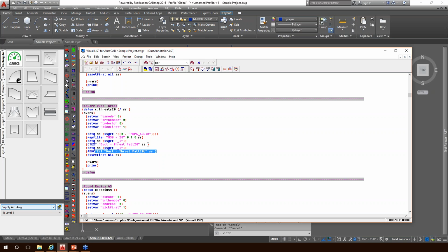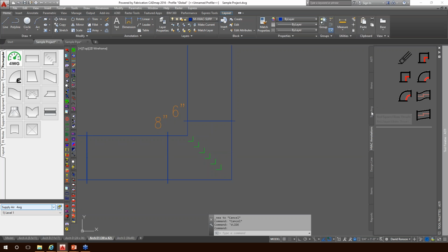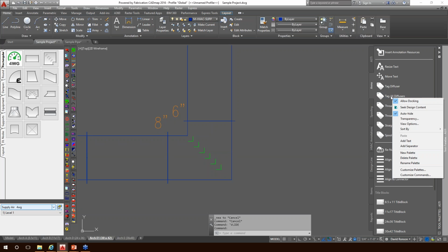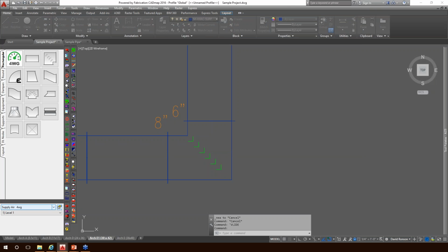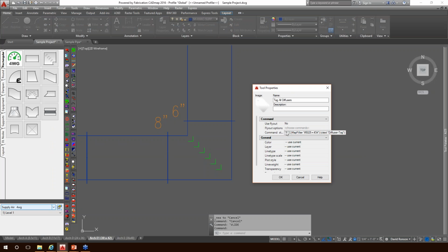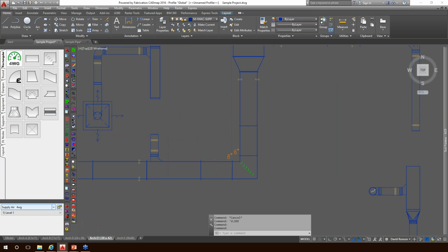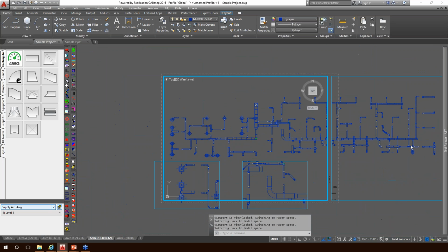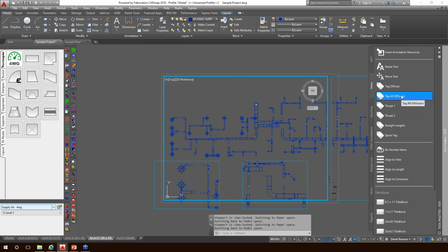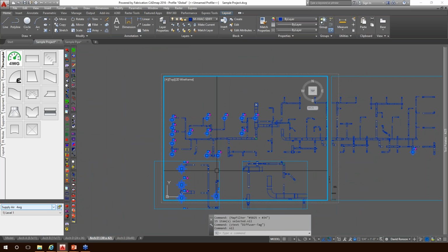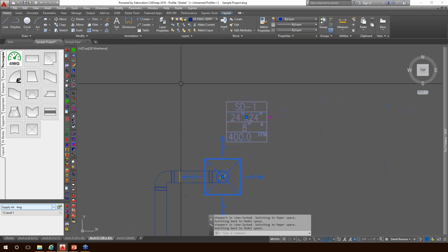All right, there's a couple ways you can do this. There's one other way, it's a macro. You may not be able to or need to go this far with it. You can use a macro. Scott has some really great macros he has. If you want to tag your diffusers, Scott has a macro in here for a filter, and then it's going to apply the C-text for diffuser tag. That macro is going to select all the diffusers and put in a C-text.